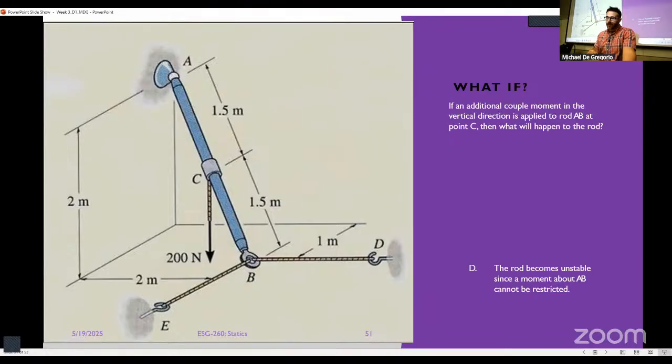Okay? So if you start doing these problems and you see, hey, I'm getting non-zero for the sum of my moments, check to see if you're statically determinate. Most of the time, the problems are not. I think it's an interesting case to look at, and it's important for you guys to be able to pick out when something is not working and the reason why, right? And it's an actual application, right?